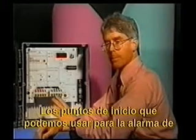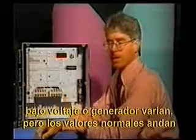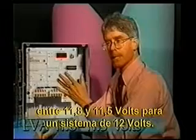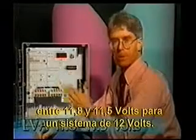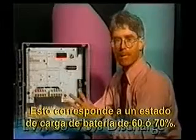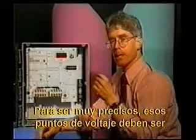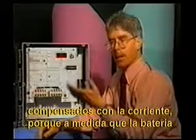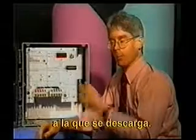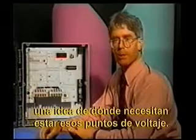The set points that we might use for the low voltage alarm or the low voltage generator start conditions vary, but typically the values that we'd want to look at are anywhere between 11.8 and 11.5 volts for a typical 12-volt system. This corresponds to roughly about 60 or 70% state of charge for a battery. To be very precise, those voltage points should be current compensated, because as a battery is discharged, its voltage will depend on the rate at which it's discharged. But these general numbers that I've given you are a rough guideline just to give you a sense of where those voltage points might need to be.